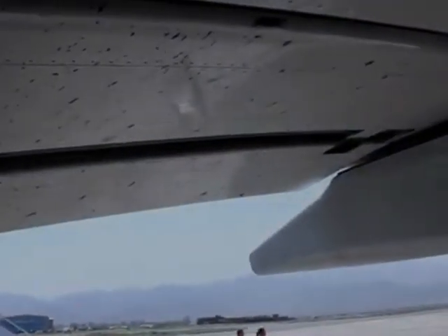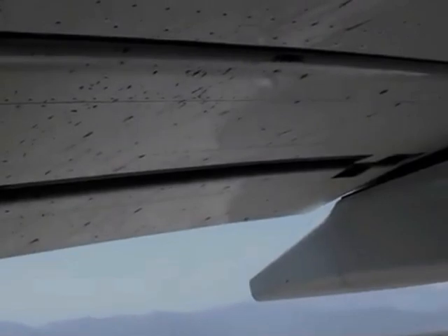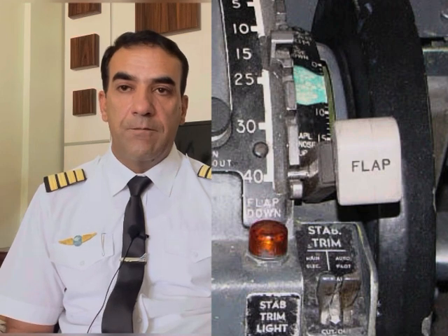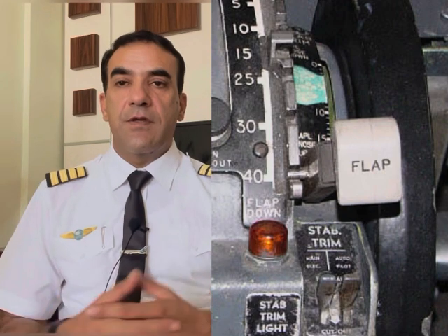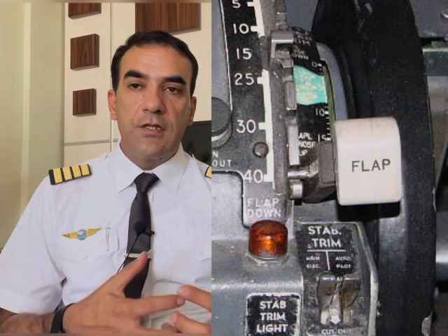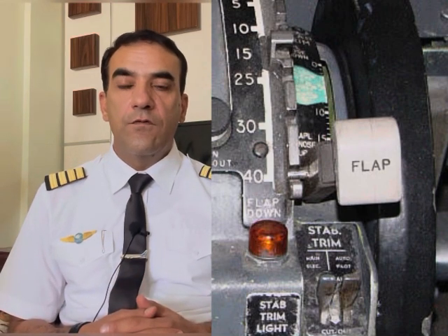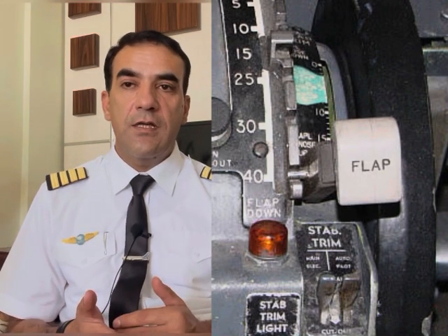The load relief system of the trailing edge flaps comes into effect, or arms, when the trailing edge flaps are extended to 40 degrees. So if the speed during the approach for landing increases beyond a predetermined limit, the load relief system will automatically move the trailing edge flaps from 40 degrees to 30 degrees. This is to prevent the flaps from being stressed and damaged due to the high speed.